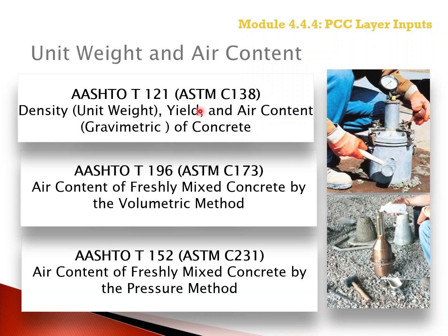The entrained air content is vital for freeze-thaw durability and needs to be checked prior to placement of the concrete. The entrained air content can be determined in several ways, but is most frequently tested with one of the devices pictured on the slide.